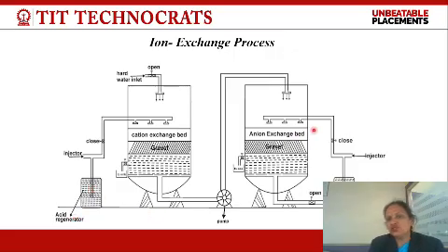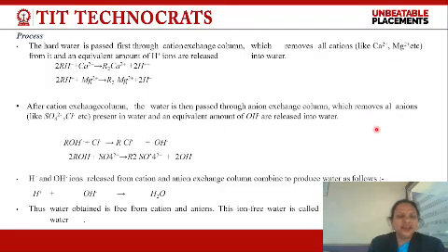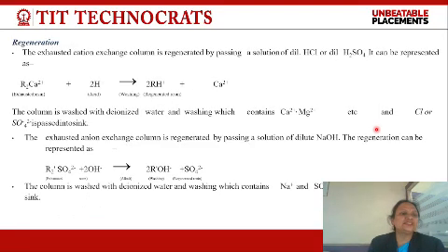And this anion exchanger bed will be regenerated with an alkaline regenerator like ammonium hydroxide. This is the injector. We can send these regenerators through this injector forcefully. And when they wash the cation and anion exchanger beds, they will be regenerated to perform the next reaction.